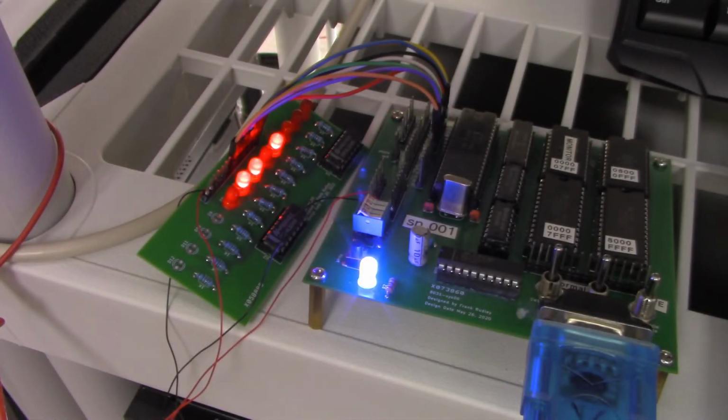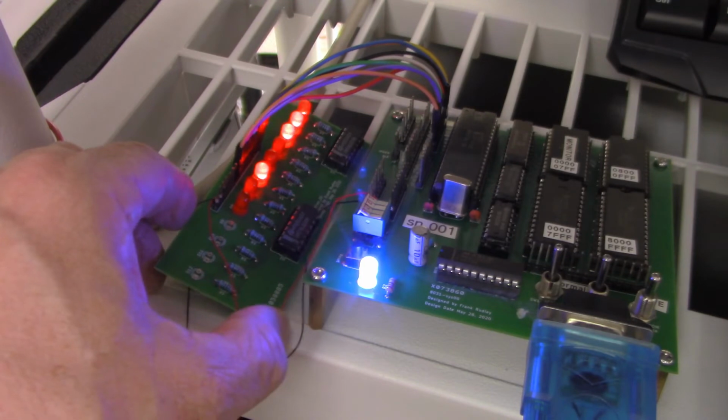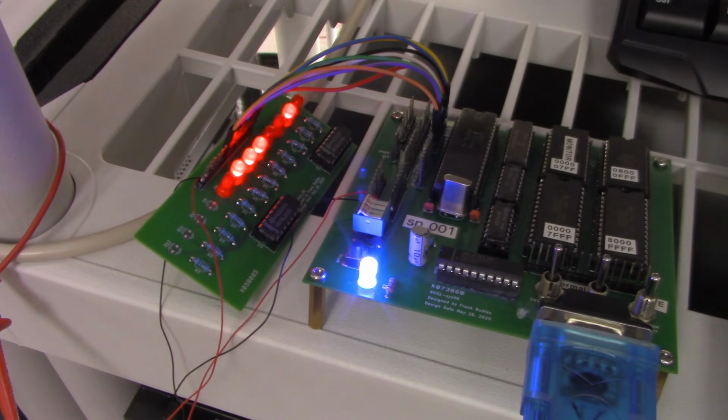Yeah, so now you can see that it's incrementing at a much slower rate. So we have a delay within a delay. So you could actually see the first light blinking there, which represents that delay on a delay. And so this is a nested delay loop, and you can see the action of the binary counter. It's an 8-bit counter that goes all the way from 0 to 255 and then repeats itself over again. So we had to add a lot more delay in there to be able to see the effect of the binary counter to verify that that was working.